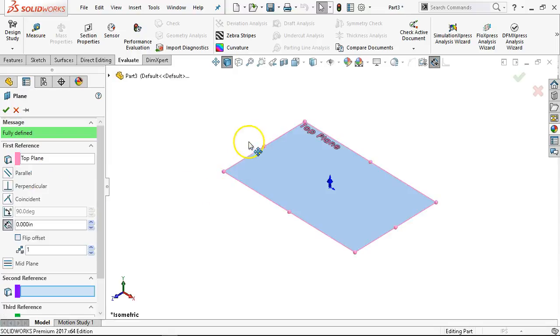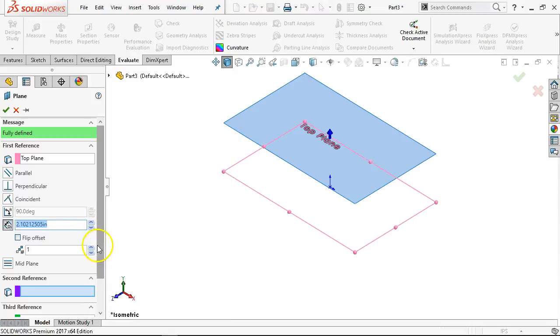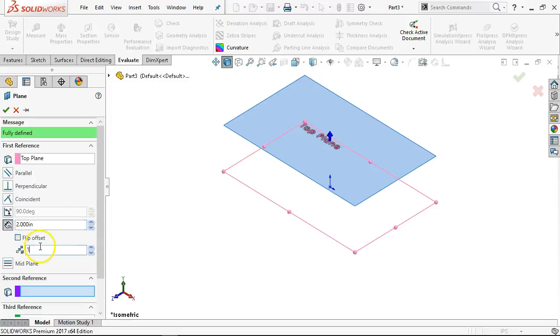If I do the control select and drag, I just need to determine how many loft sections I want. I don't know what the transitions are going to be, but let's go 2 inches, and I want 10 of them, that will put me back at 20 inches. But I don't want to draw that many, so 5 of them will put me at 10 inches.